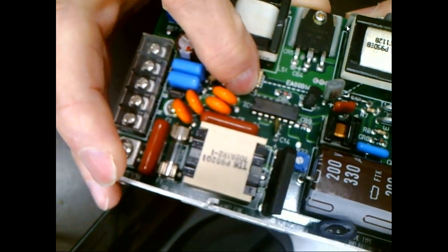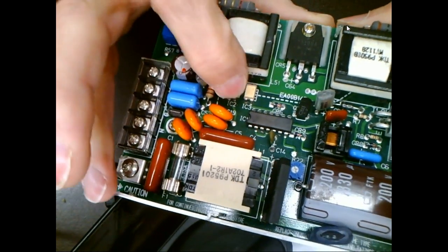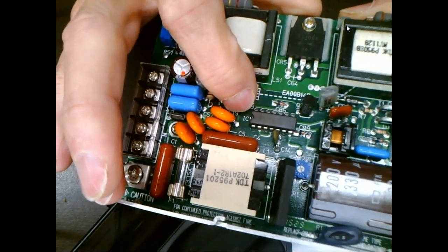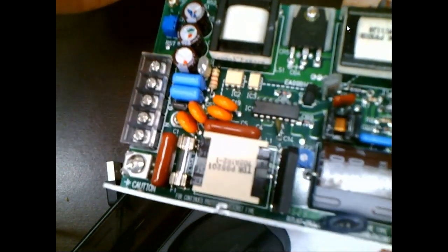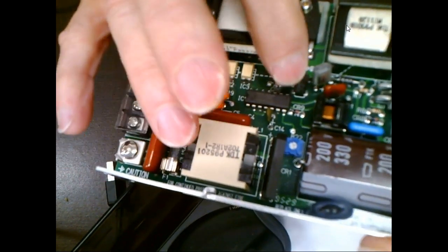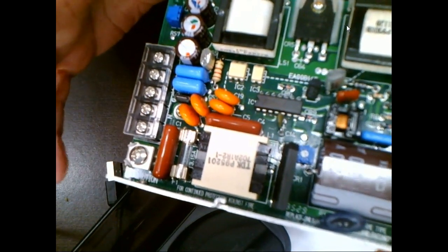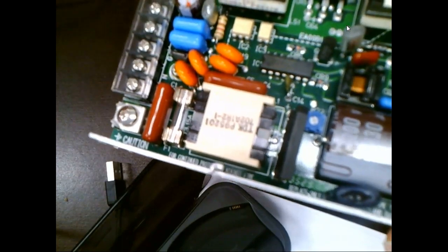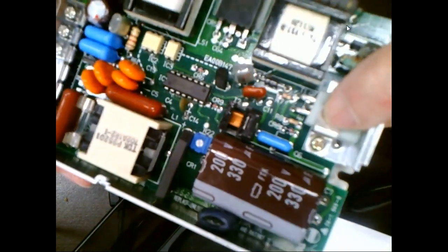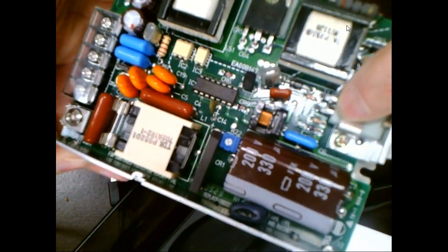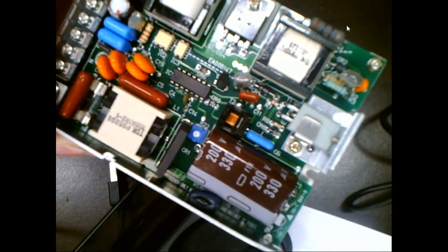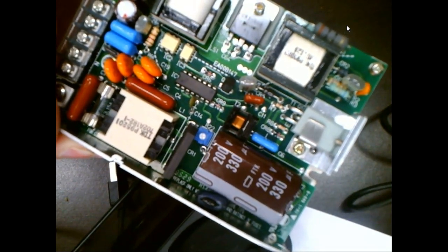Integrated circuits, this guy's using one of the designators. They call them ICs, but normally what they try to do is designate with one letter. Every once in a while you'll see people say IC for integrated circuit, but most of the time it's going to be called U, U1, U2. So if I looked at this thing right here, and it had U1 on it, then this wouldn't be a transistor. It would be an integrated circuit that only needed 3 pins to the outside world, right? You understand? Like a voltage regulator.